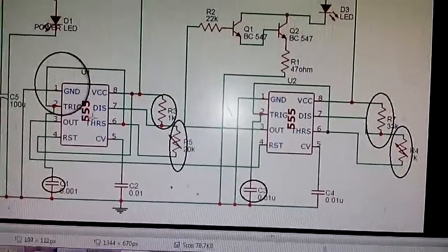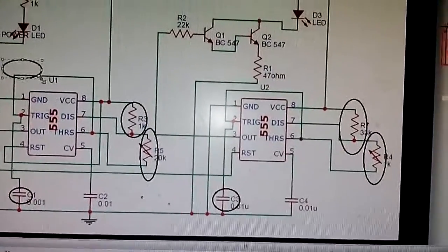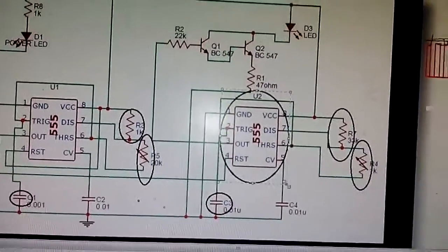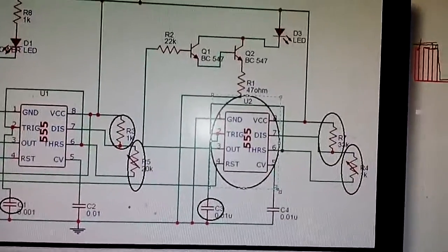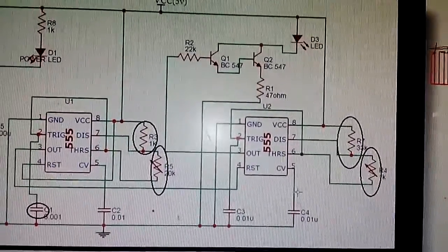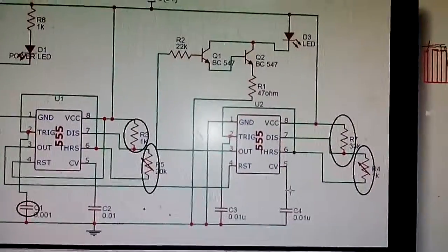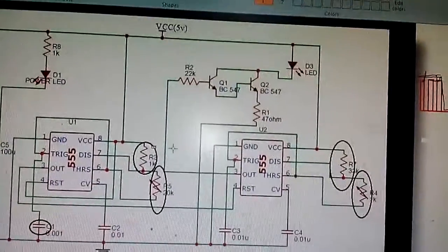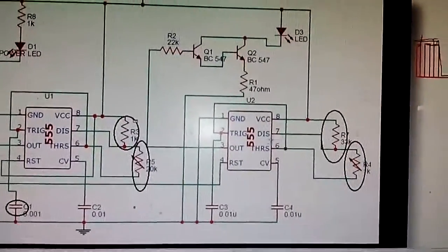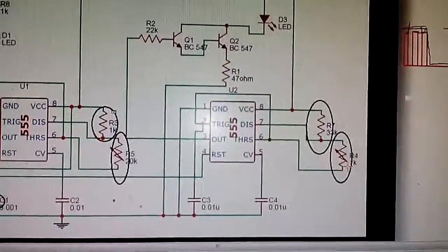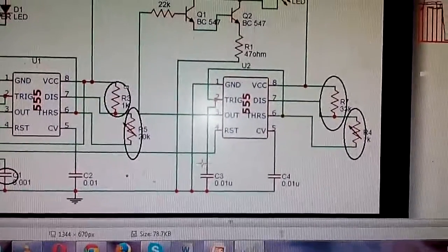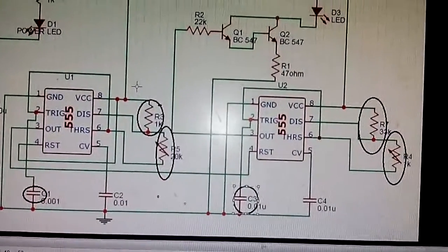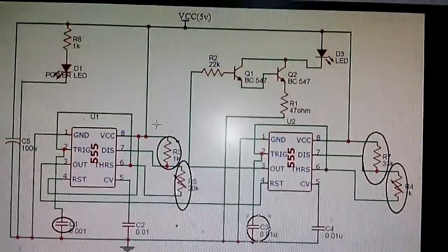You can use this timer for the modulating signal, for 10 hertz or 100 hertz, whatever you need, and you can use this one for the purpose of the 38 kilohertz carrier. I think you all know about the design of an astable multivibrator using the 555 timer. So design the values of the resistances RA, RB, and C for both the 38 kilohertz and the modulating signal of 10 hertz or 100 hertz. Thank you. I think you can make it.